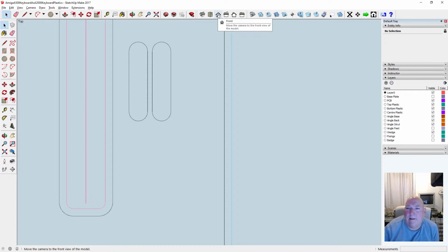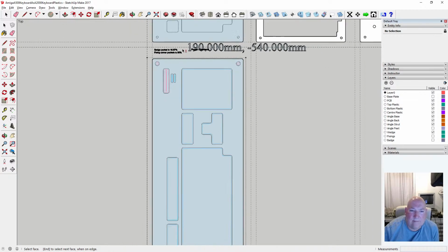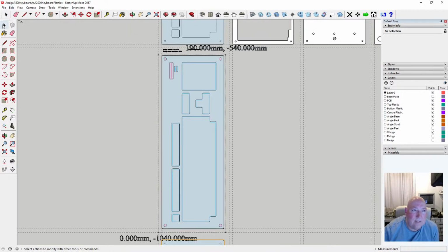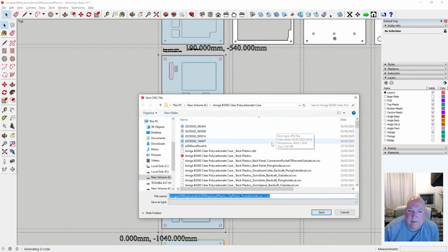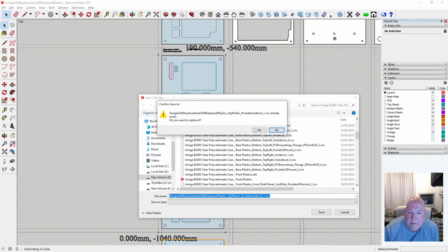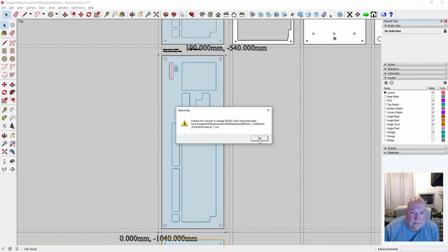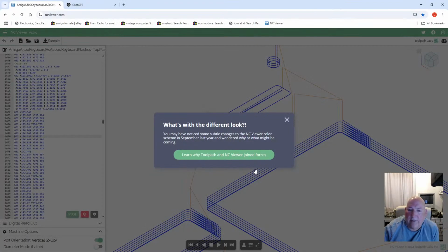So we're going to go do a pocket again. Oh no, it's an inside cut, not a pocket. Yeah, see how it does it now, better. Proper tool path. Right, so that was the only anomaly I could see. So we'll create that again, overwrite that same file. That's it. Just overwrite the same one. Finish. Let's have another look at it.